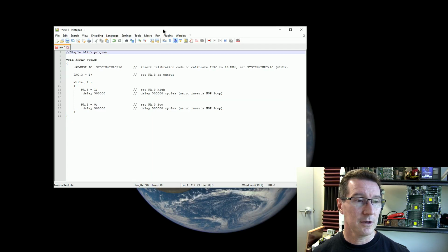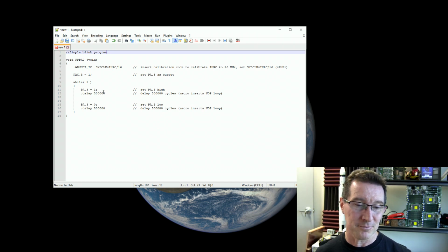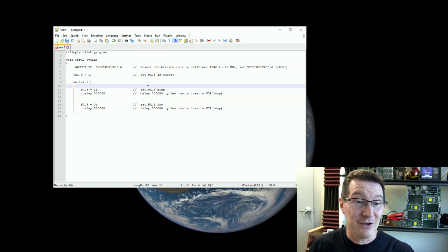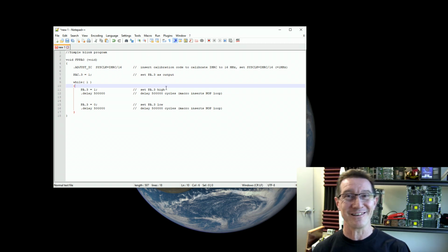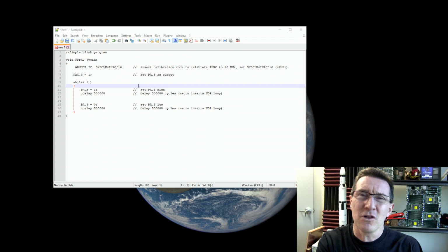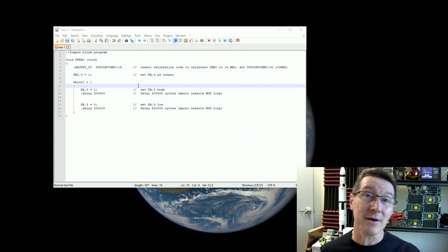nah. So I thought what I'd do is just use Notepad++ here. I cut and pasted this code. I don't expect it to work because I suspect it only works with the Padauk programmer environment's quasi-C compiler, but it's worth a shot. Basically, you're just learning as I learn here. I'm just going through until I get something that works. But the good thing about this is that this is how you can expect it to go if you're in the same position I am: I want to use these Padauk microcontrollers for something, I've got a specific application, I've got to build up the hardware, download all the stuff and figure out how all this works.